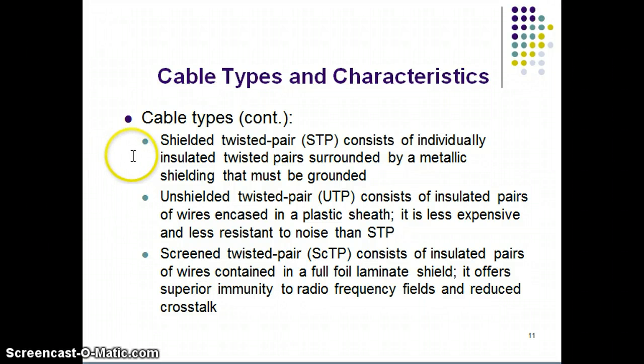The next most common one that we find is this shielded twisted pair, and in that case each pair has its own shield around the pair. The pair is twisted, has a foil shield. Each pair has a foil shield, and then there is another shield that goes around all 4 pairs. And that shield gets terminated to our bonding and grounding system through the connectors, through the equipment chassis. So in that case, the shield is trying to eliminate noise from entering the cable. And by the way, it works the other way around too. It eliminates noise from leaving the cable.